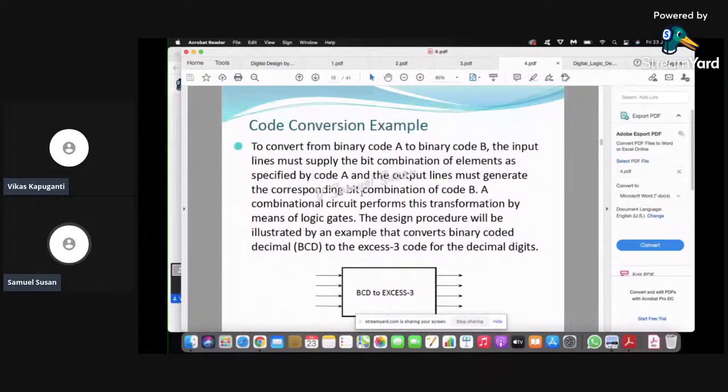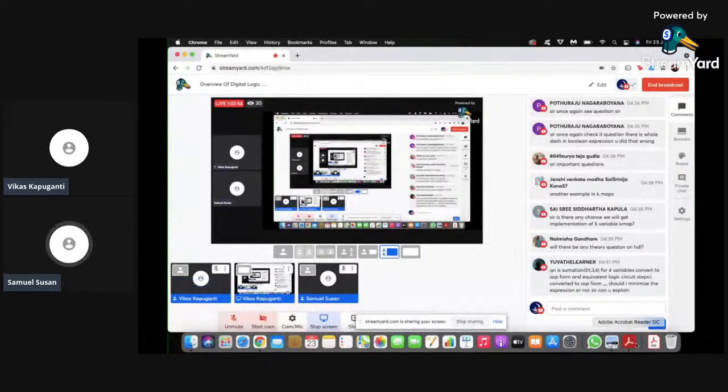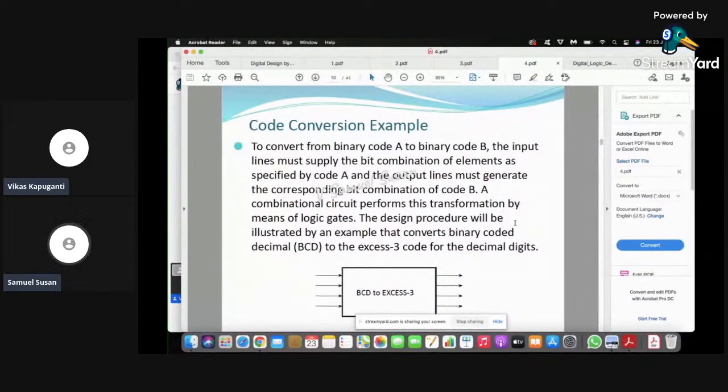Designing a combinational circuit, if the definition is given formally, you need to first formulate the table. First of all, in the block diagram, you can see the number of inputs and outputs. Then we go with the formation of the table based on the statements given. For the outputs, you can find the equations using a K-map with the respective inputs.